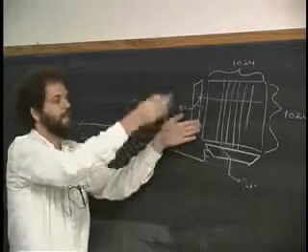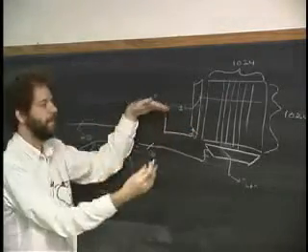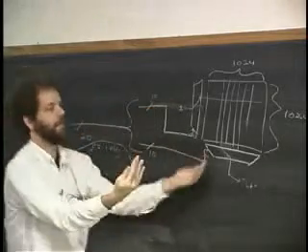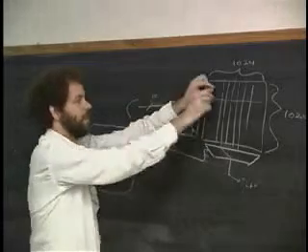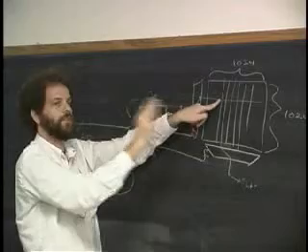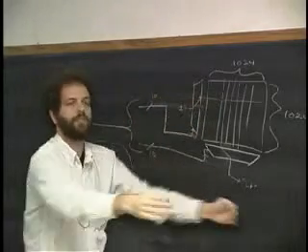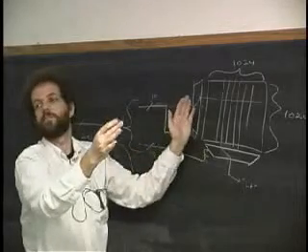And if I take this and replicate it 32 times like so, and have all of them do the same thing, they're all going to kind of go up like this, and they're all going to go across like this in step with each other. Whichever particular place in X and Y I choose here will be the same place along all 32 planes, then I'll get 32 bits out of storage from this 1 mega word system that I have.